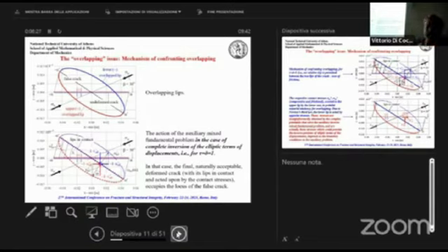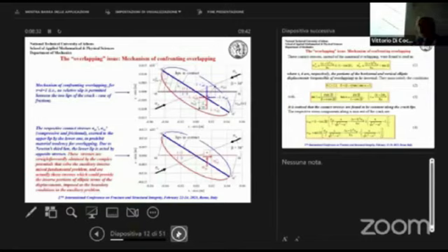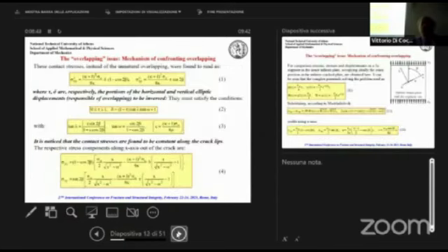And that is to avoid overlapping, but in this case, we have to take into account the inevitably generated contact stresses. What was the contribution of this PhD is that it was possible to calculate the contact stresses in case of an infinite domain. You can see here the expressions for the contact stresses along the lips. And what is to be emphasized is that this inversion is partial.